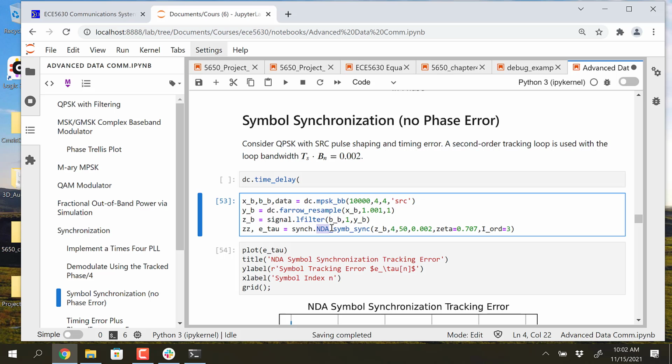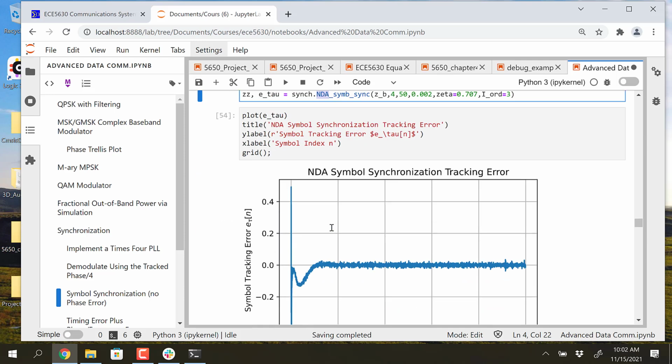So this algorithm is an amazing algorithm that carrier doesn't have to be there either. I don't have to have knowledge of the data. I can actually find the edges on BPSK, QPSK, MQAM, or anything. You can find transitions from any of those waveform types. And you don't have to have the carrier done first. So that's one of the cool things about this algorithm.